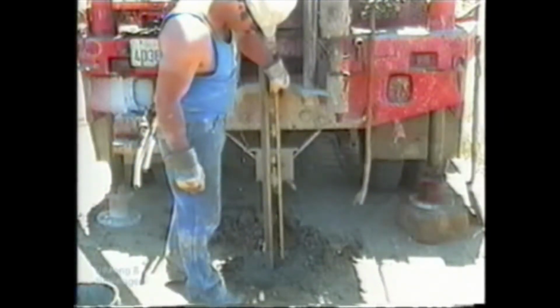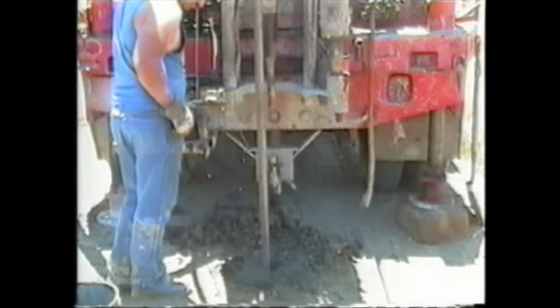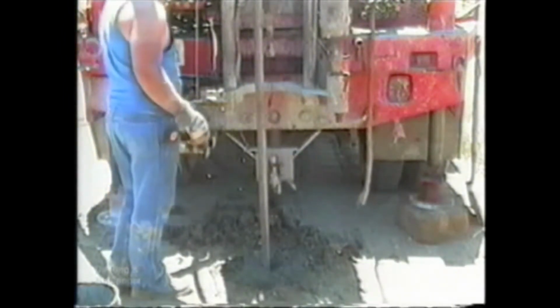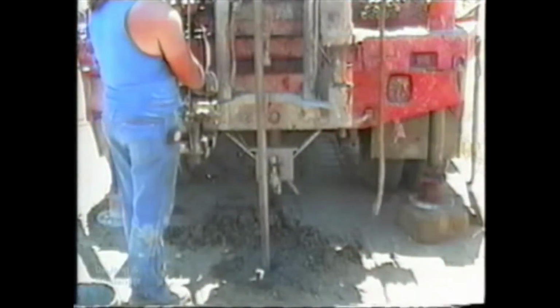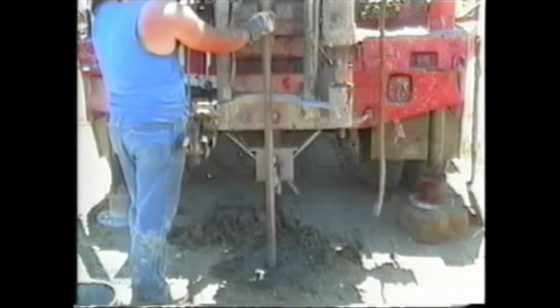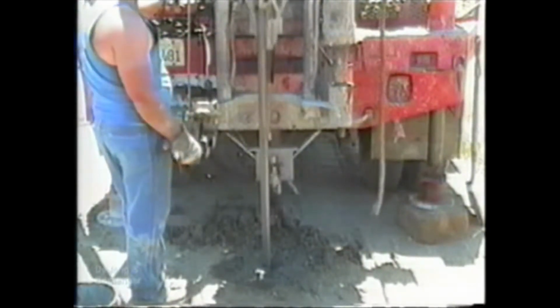To take a sample, a tube is attached to the bottom of the drill rods and lowered into the borehole. The sampler is then pushed downward from the bottom of the hole, a distance about 5 inches less than the length of the tube. To minimize the sample disturbance, the sampler is pushed into the ground at a high constant speed. The sampler should not be driven by a hammer, as this increases sample disturbance. After the sampler has been pushed down, the drill rods are rotated to shear the end of the sample, and the sampler is removed.